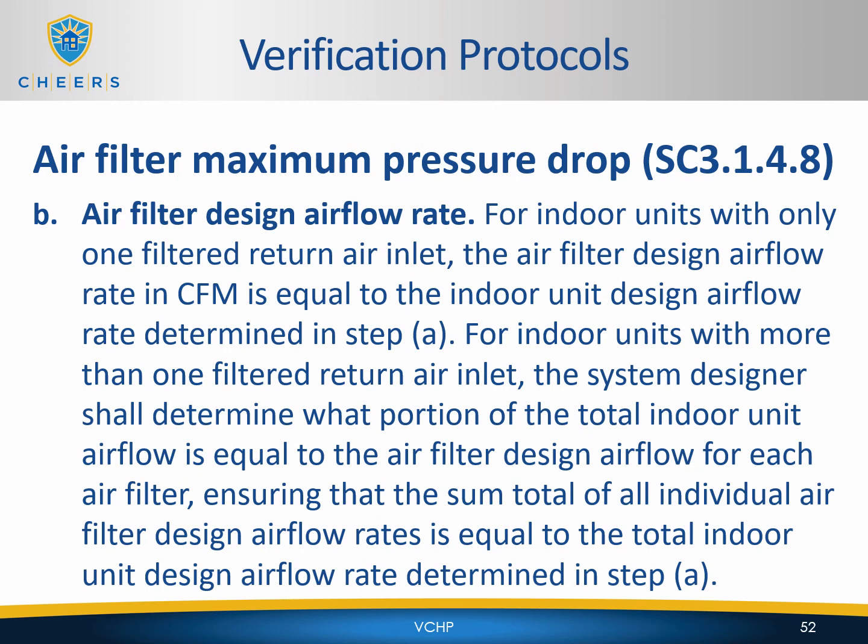Air filter design airflow rate. For indoor units with only one filtered return air inlet, the air filter design airflow rate in CFM is equal to the indoor unit design airflow rate determined in step A. For indoor units with more than one filtered return air inlet, the system designer shall determine what portion of the total indoor unit airflow is equal to the air filter design airflow for each air filter, ensuring that the sum total of all individual air filter design airflow rates is equal to the total indoor unit design airflow rate determined in step A.